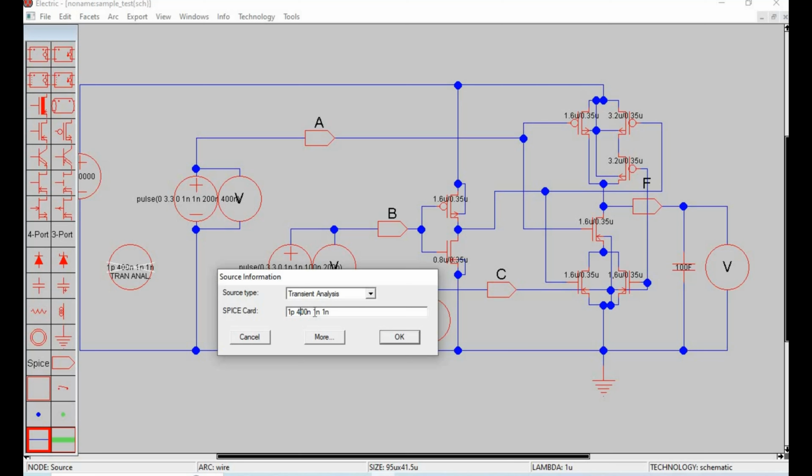Since we just want to determine if we will have the correct function, just use 1 nano. So we can have a bigger step size since we only want to determine if we would get the same result from our truth table in this circuit.